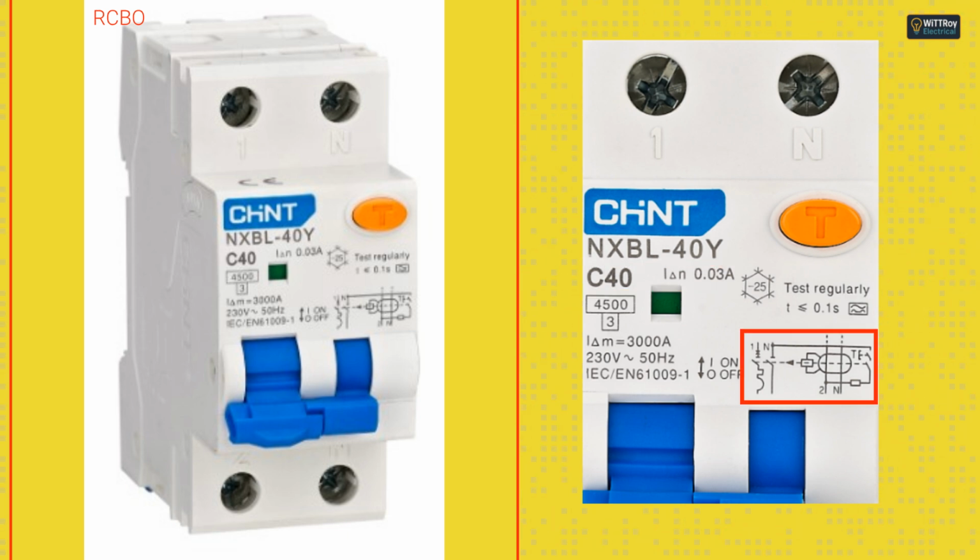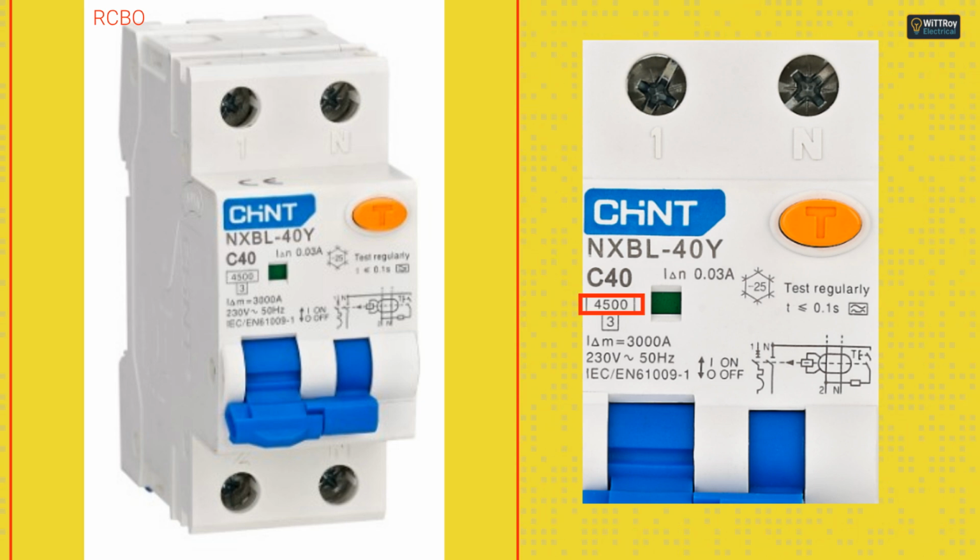From the diagram, I can see both the MCB symbol and the RCD symbol. So this device combines MCB protection and RCD protection. The label shows 4,500. So the short circuit breaking capacity is 4,500 amps or 4.5 kA. So this is a C40 30 milliamp type A RCBO. It provides earth leakage, overload and short circuit protection.